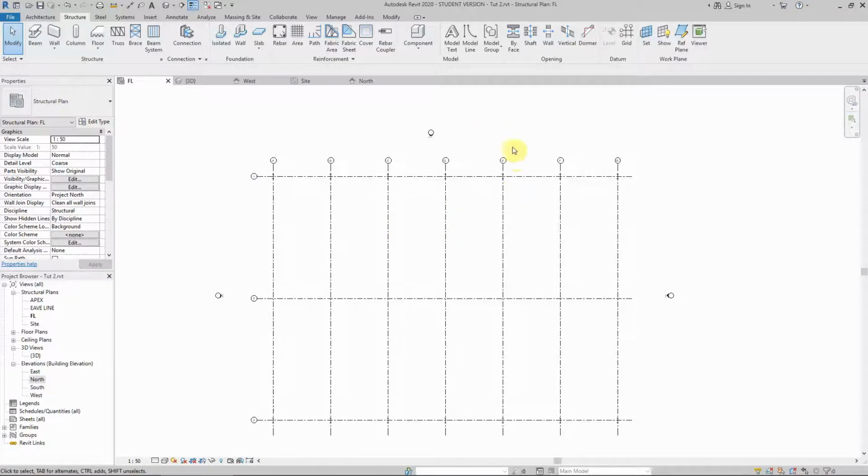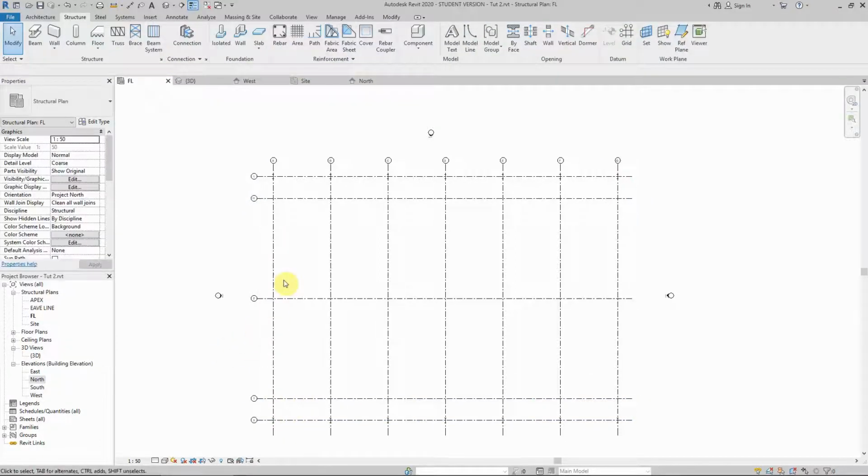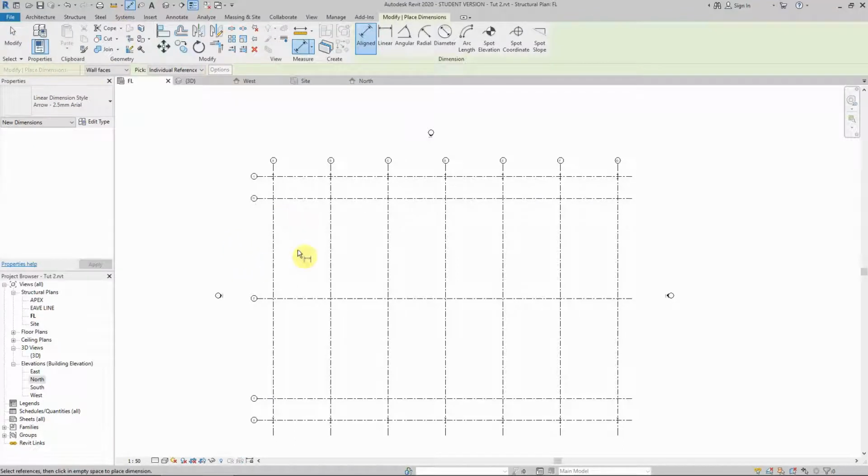To create a grid line there, we'll go to grid offset. I'm just going to offset it without worrying about the measurement and to create a precise distance, I'm just going to offset it 2500 at this point here to this side and another one to that side. Why did we do that? Because we have an easier way to make sure this grid line is in the center.